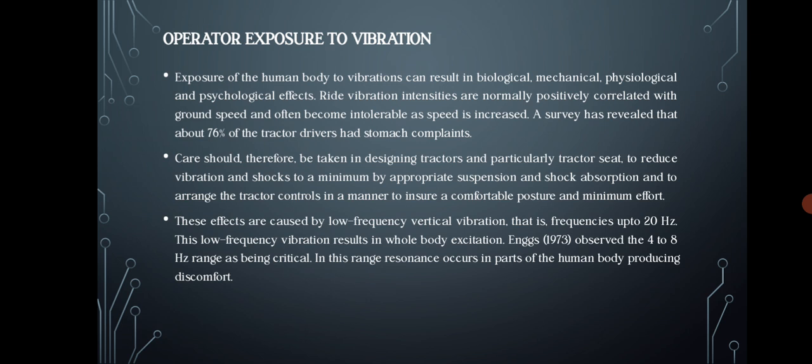These low frequency vibrations result in whole body excitations. Engineers observe the 4 to 8 Hz range as being critical. In this range, resonance occurs in parts of the human body, producing discomfort.